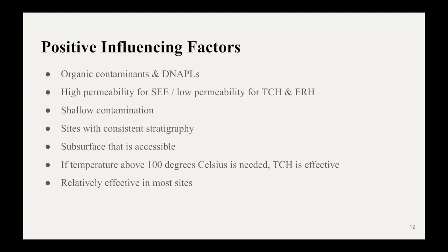And then additionally, less energy will be needed if the contamination is shallow, due to the fact that heat takes a while to spread. So the less deep the contamination is, the less time it would take for the heat to build up in the subsurface. And then less energy requirements means less expenses as well, making it more profitable for whoever's cleaning up the contaminated aquifer site.